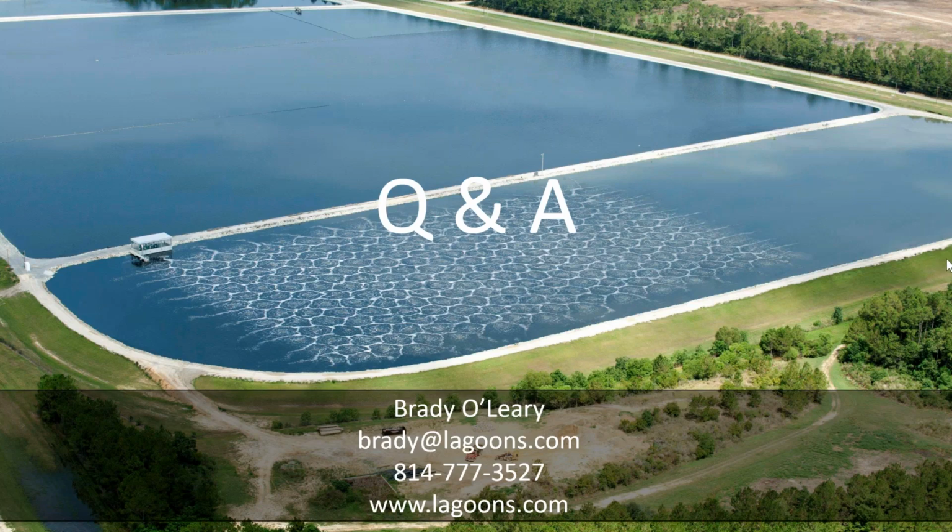How to solve settled sludge in a facultative lagoon. Okay, I'm just going to stop on that one. I've got a lot more questions here. We'll answer the rest of these after the fact with an email. But with settled sludge, you typically add aeration or you remove it. It's either physical removal, or you need to add aeration or some kind of bacterial treatment.